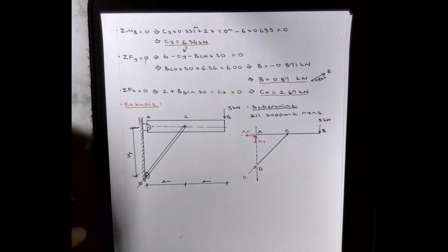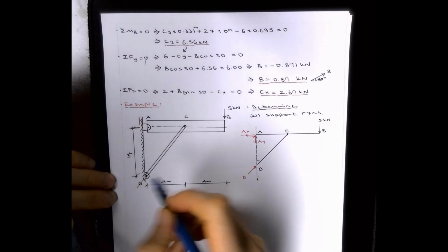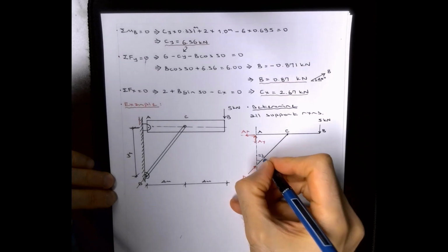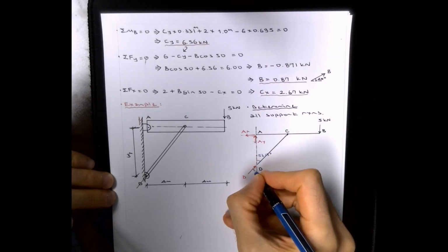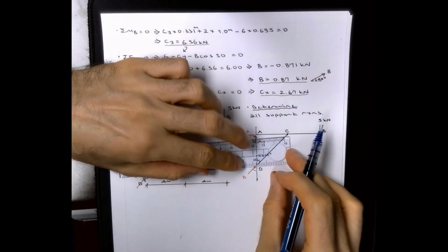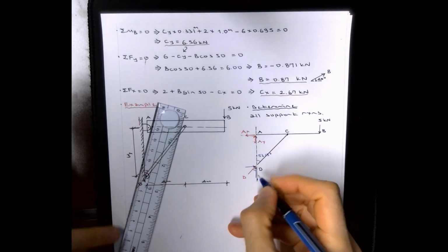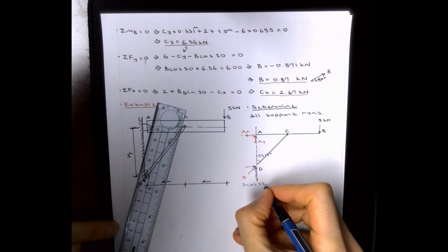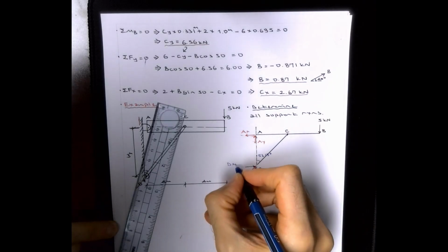Let's just get some calculated. This is a 3, 4, 5 triangle. If you calculate this angle, you would find it to be 53.13 degrees, and that is the same as this angle, because sooner or later we would need force components. As you know, adjacent is always cosine. D cosine 53.13, and then this is going to be D sine 53.13.